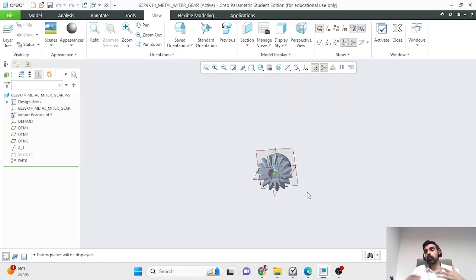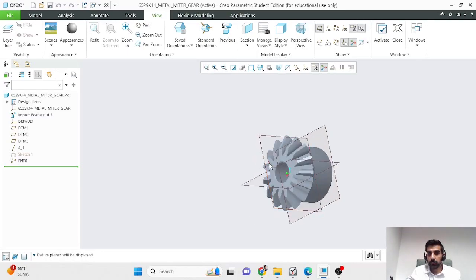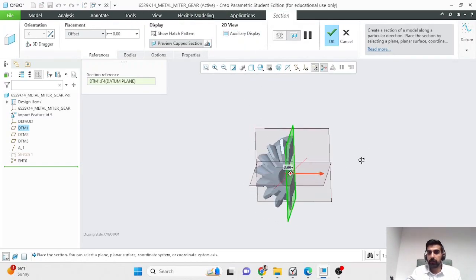We can generate section views. Section views are views which cut through our 3D models, and they're very useful at displaying the insides of solid entities to convey details about the interior structure of our design. So there isn't really any region over here, but let's say that there was some keyhole over here and we wanted to convey the details of that keyhole. What we can do is to remove everything to the right of this plane.